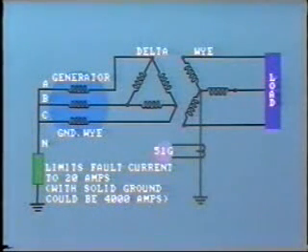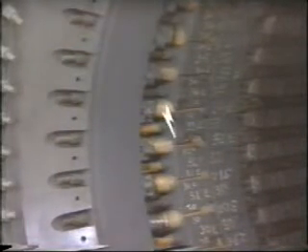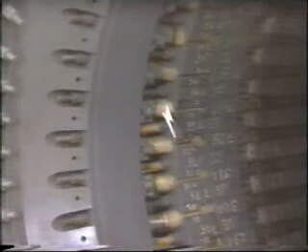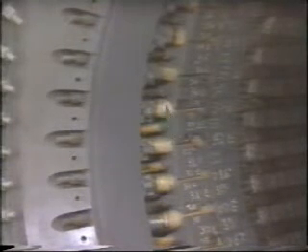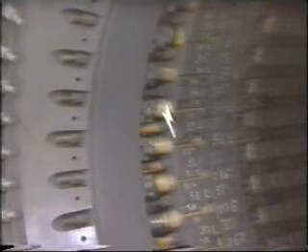But what is the advantage of impedance grounding? Well, by reducing the magnitude of fault current, we are reducing the amount of damage that it can do. For example, suppose the ground fault is in the generator winding itself. The very high fault current and resultant arc jumping from the winding to the stator laminations would probably burn and seriously damage the generator.